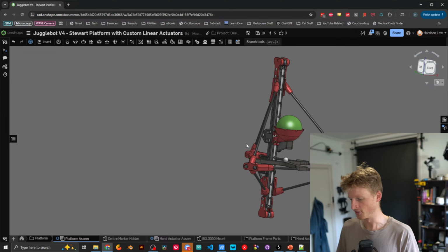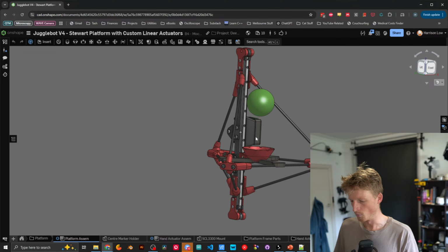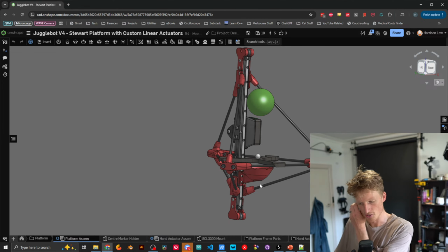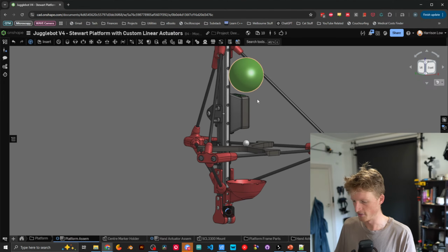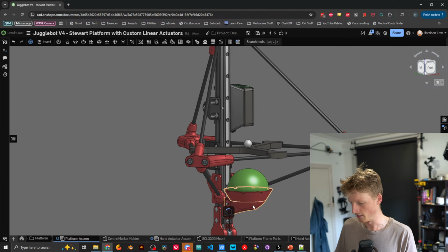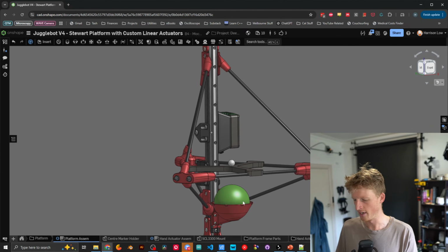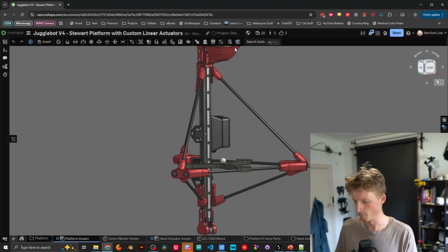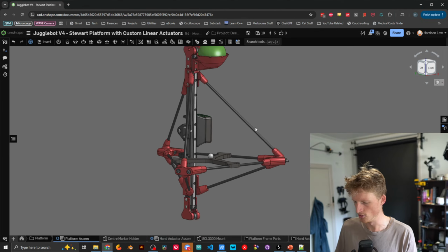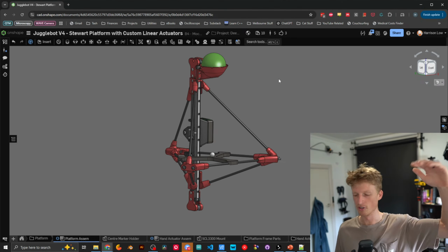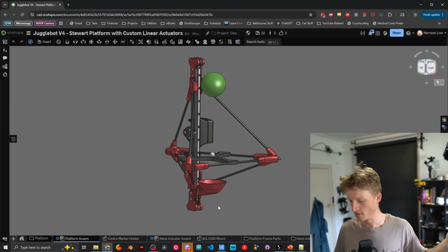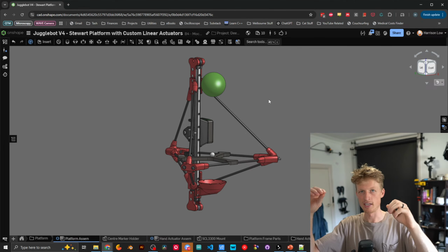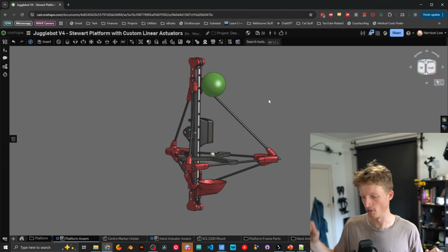Now for the hand, I've been planning to just use a separate offset, so that way I can calibrate it, probably with the tracked ball in the hand, and move it the whole way either up or down, probably up so that it's not getting blocked by this tube. I can just move it to a known location and then say, yep, the hand zero point, which would be down the bottom, is here with respect to the platform origin.